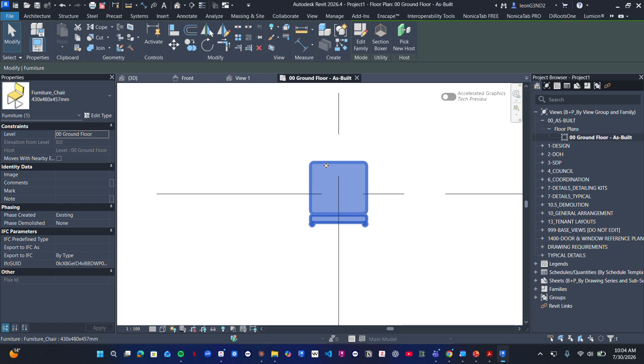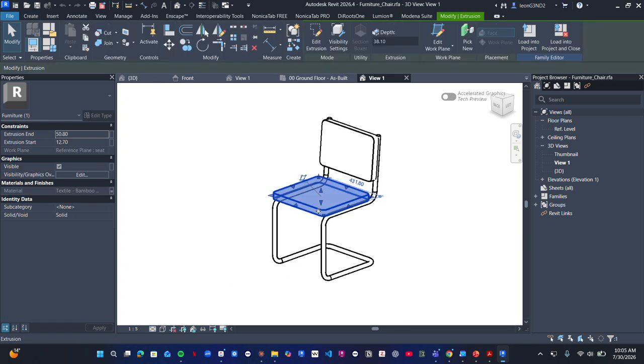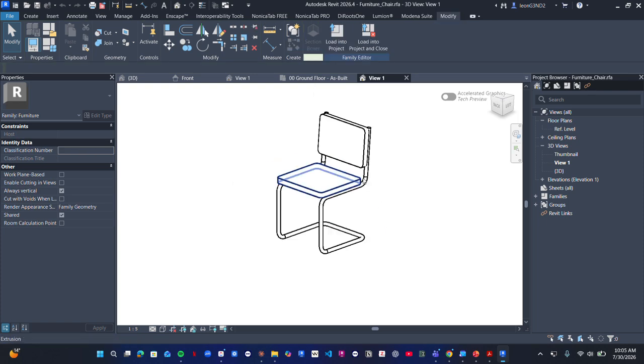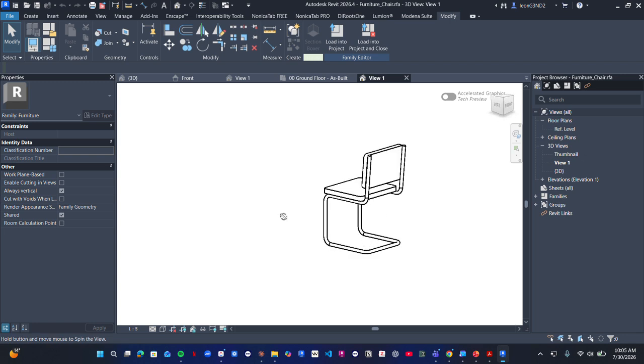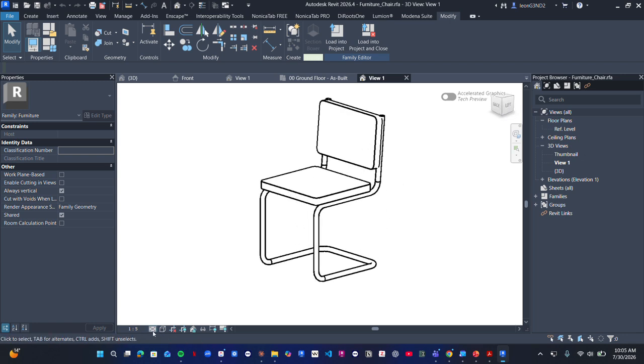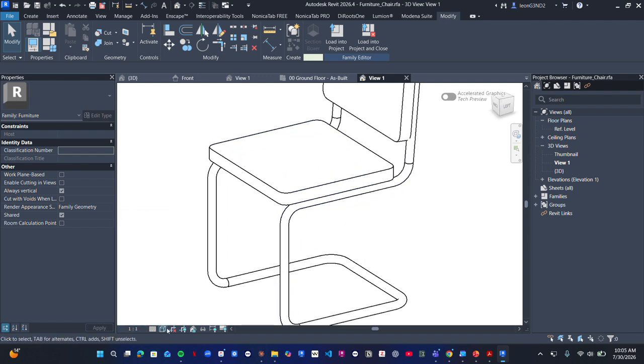Okay, I've just opened a new model and loaded a family that's in a metric value just for easier context. So I'll select this chair here, I'll say edit family. So you can see here, this is our family. You can see this family is a bit less parametric in the way it was created. It's a bit more model element based. If I want to change the way in which this looks, I can just change the scale here. So you can see this starts giving me more detail.